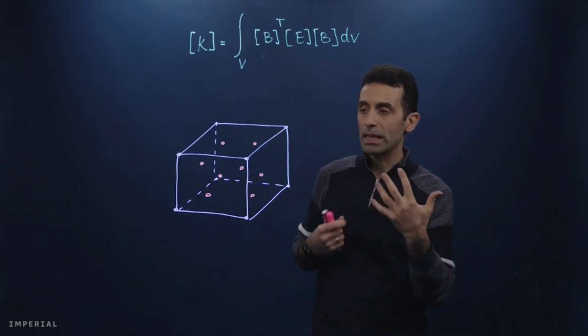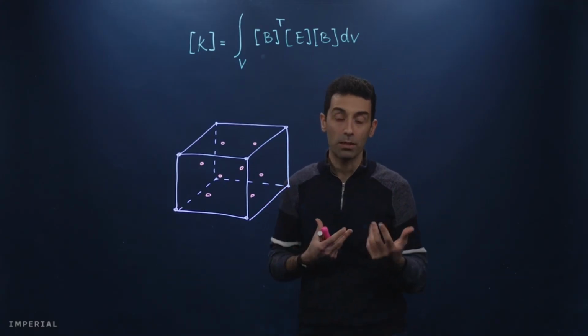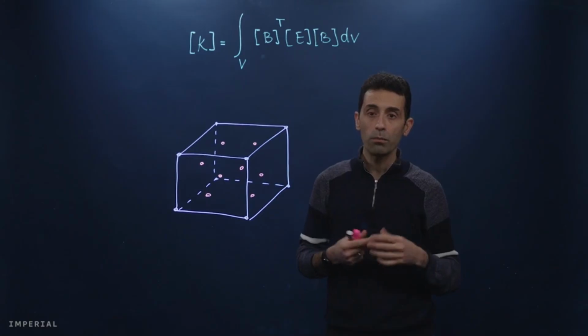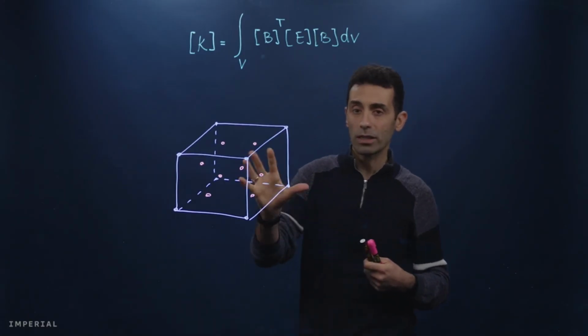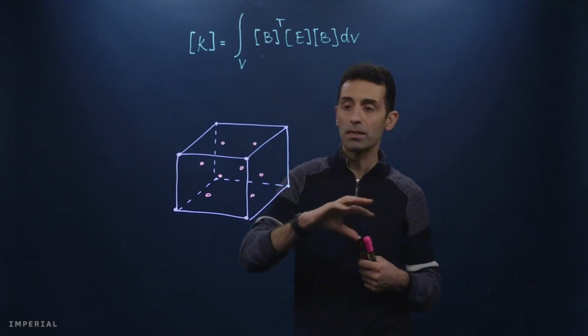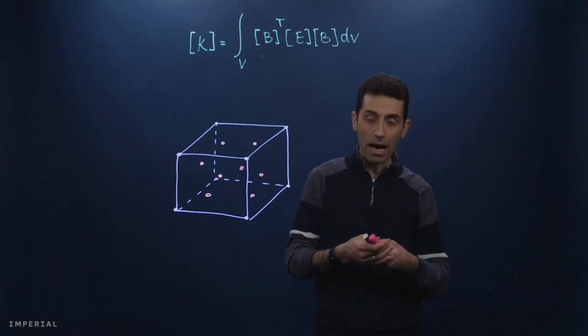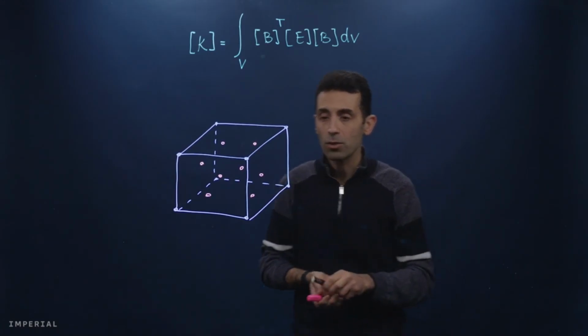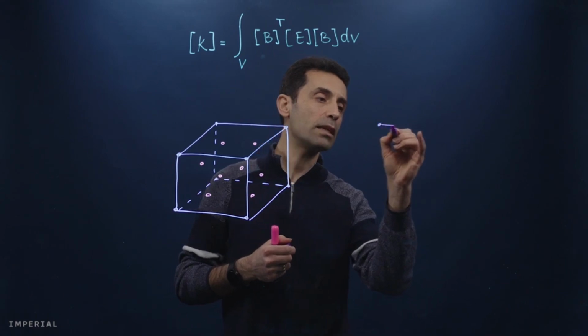But this can lead to some challenges, like when your material is nearly incompressible, like in brain, or most elastomers that we are dealing with. Then using full integration may lead to some instability problems, or it may lead to over stiffness of our finite element model. So a remedy for that is to use a single integration point.